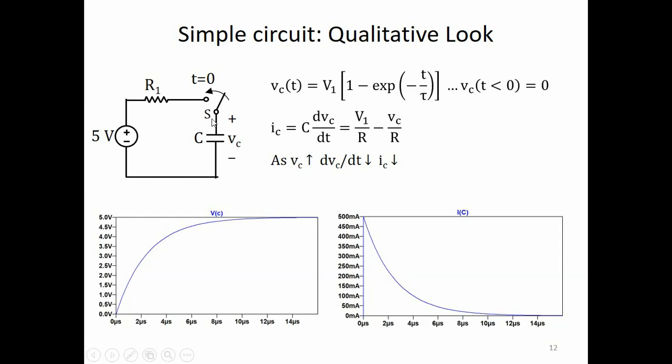In this circuit, the switch is open for a long time, and we are told that Vc for t less than 0 is 0. We always have to be told what the capacitor voltage was for t less than 0 if nothing was connected to it, because as we've seen last time, the capacitor can have a charge on it and it will retain that charge forever if it is kept open circuited. So we must be told this information if the capacitor is not connected in the circuit.